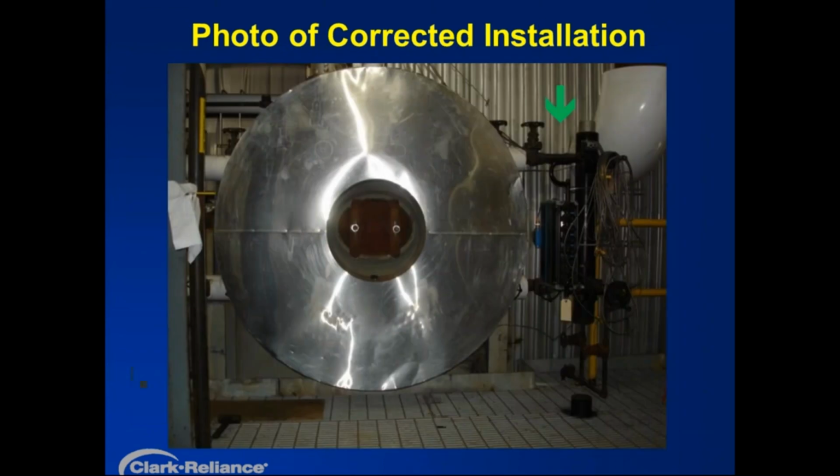And you'll see here in the next slide, the water column was remounted correctly where it needs to be on those original connections. And in summary here, we built the water column correct, the contractor did their job correct, specifying the water column. The field contractor decided to make their own decision where to mount that water column and almost put that brand new boiler at risk. Just an example of what can go wrong.